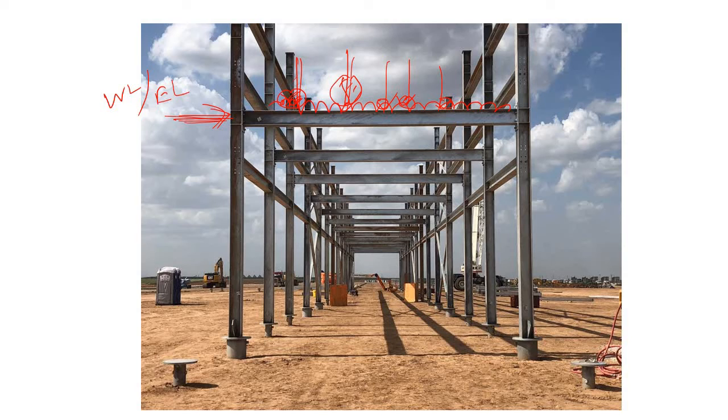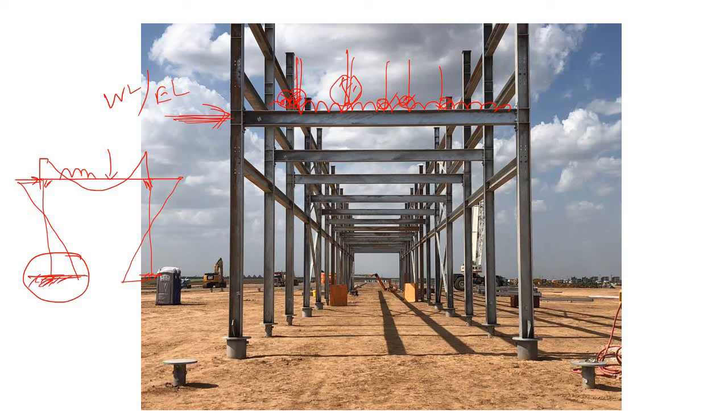Clear? So due to this type of loading, what is the bending moment diagram? If this is the portal frame, this is fixed, this is fixed, this is also fixed, and if these are the loading like this, you will have a bending moment diagram something like this. And like this. Similarly, on the right hand side also you will have a bending moment diagram like this. So here you can see, if we only consider the foundation part, due to this vertical load you will have some compressive load acting on this foundation.